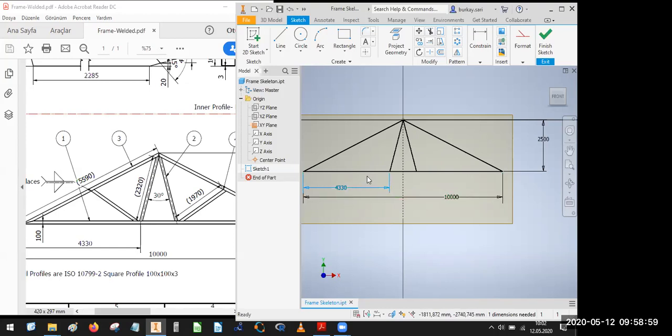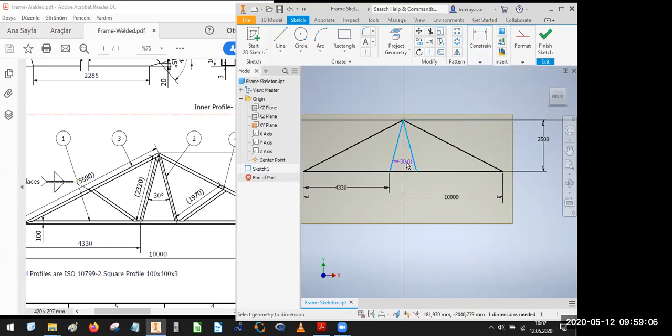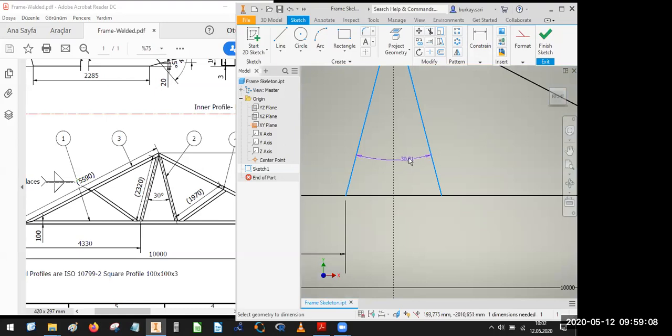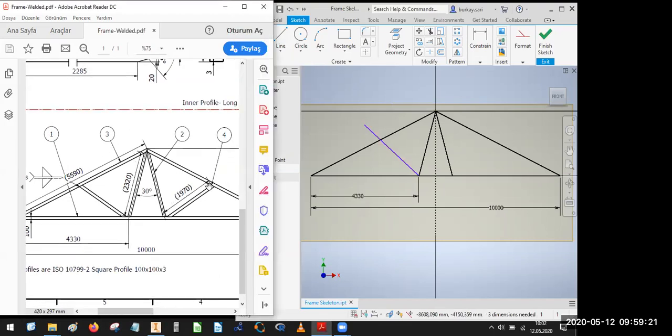Yeah, okay, anyway. We can also have this point. As you see, when you just make the angular constraint, it is almost 30 degrees, the center lines. Here, I have two lines, which is this one. And here we have a profile length almost 1,000, 970 millimeters after the trim operations. This is the length here.